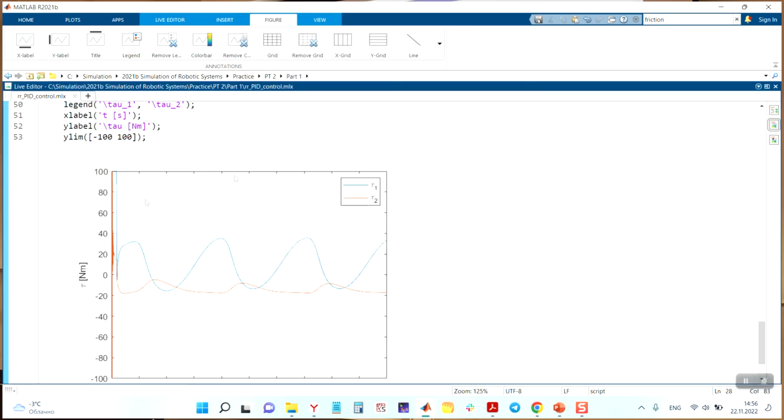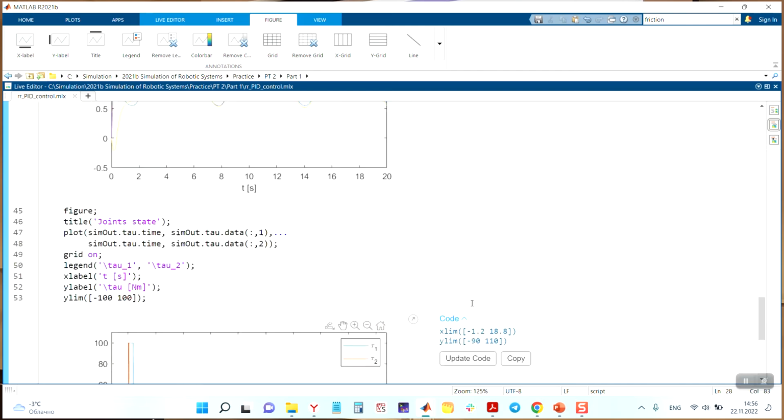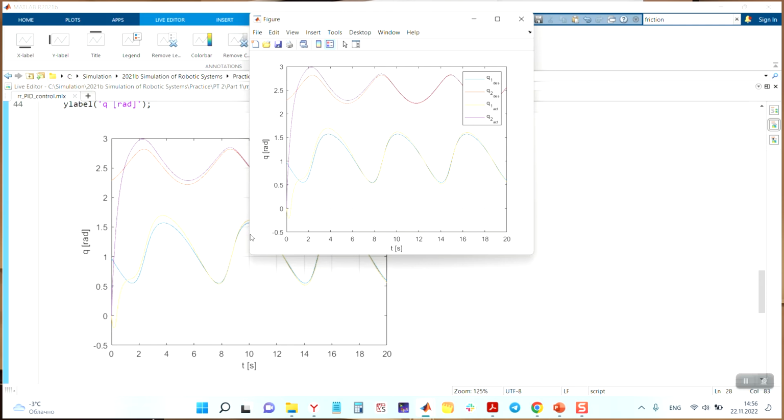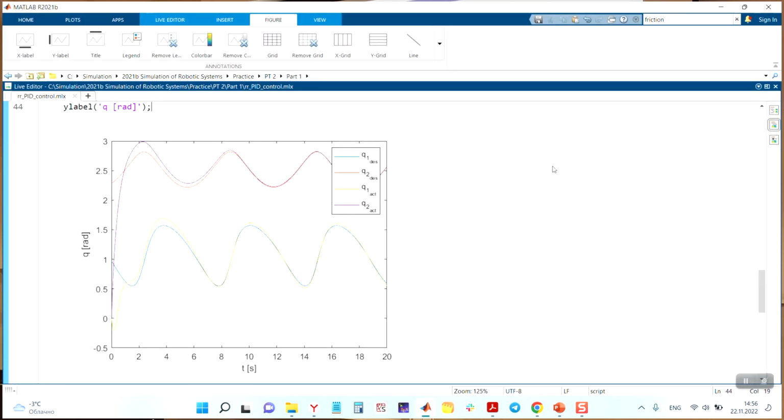We can make it even smaller. And actually, it's the reason why the settling time now is greater. Before that, it was 0.2, and now it's more than 8 seconds. Still, I suppose that if we tune another kind of coefficients, and if our initial position will be closer to the desired trajectory, the settling time will be smaller.